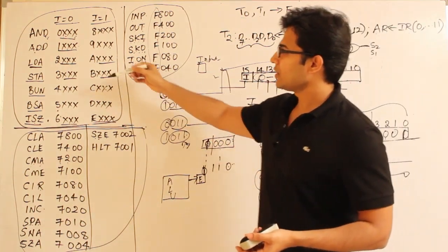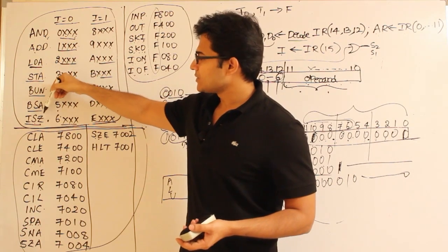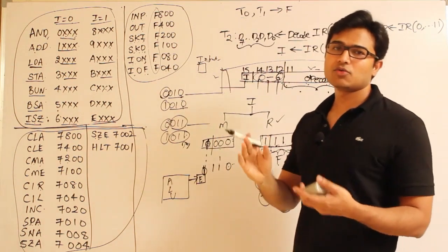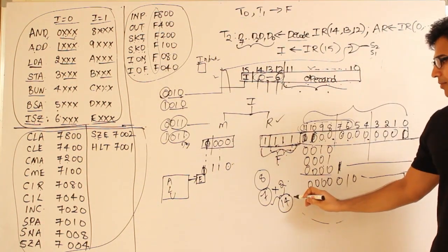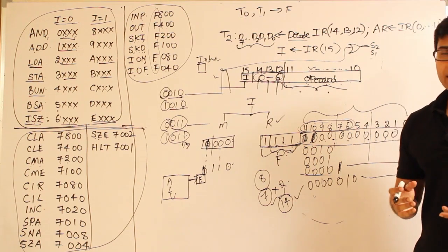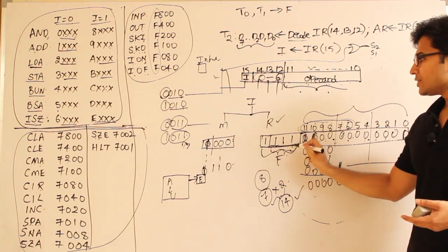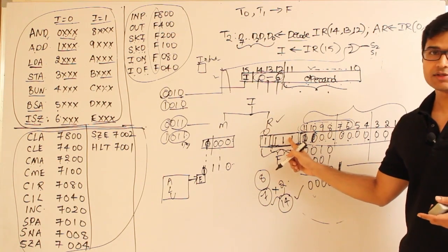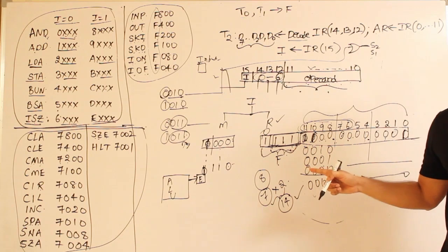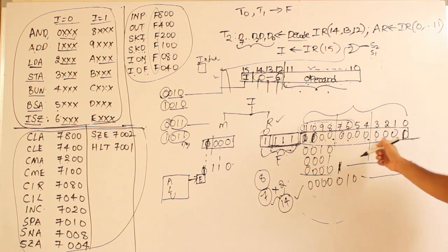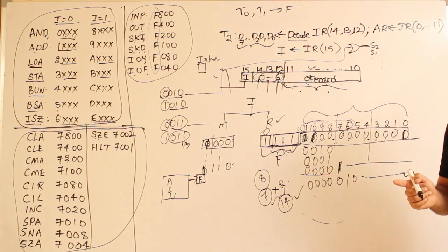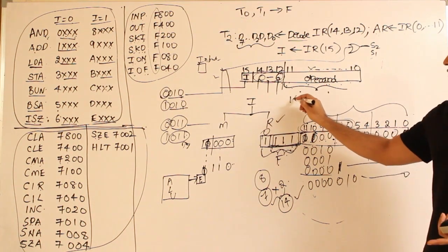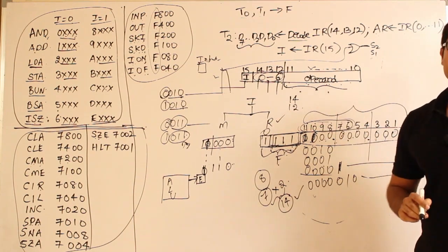You can count them, right? 1 2 3 4 5 6 7 into 2, because depending on the mode we are getting 2 instructions. So 14 memory related instructions we are able to frame, and then if you fix all these 2 ones and this one to 0, we got register related instructions. And in that register related instructions, since we don't need the second operand, for every bit we are assigning one instruction. Therefore 12 different instructions we framed. So apart from those 14, 12 we framed.